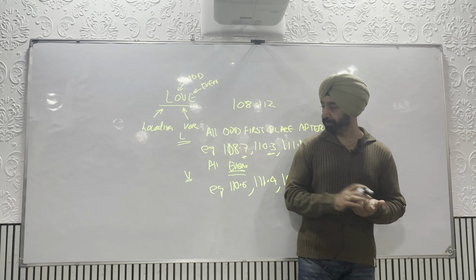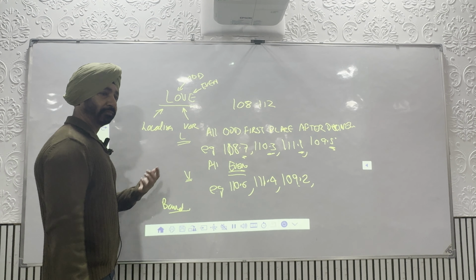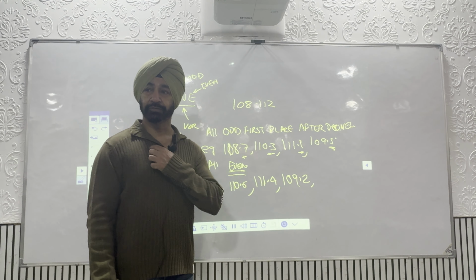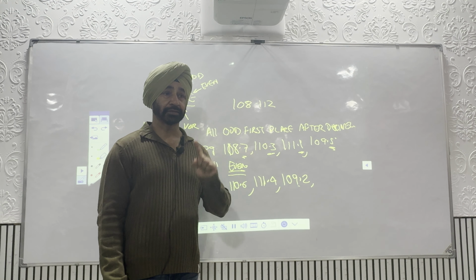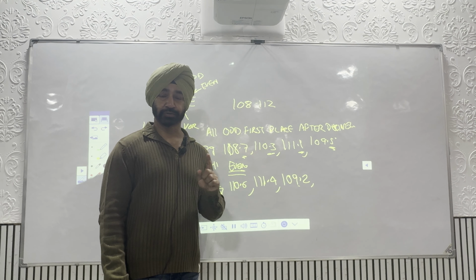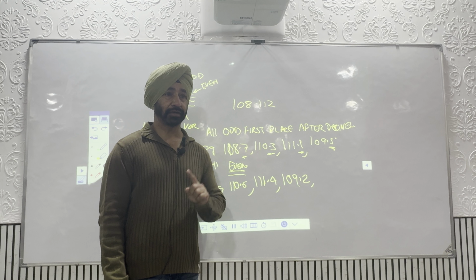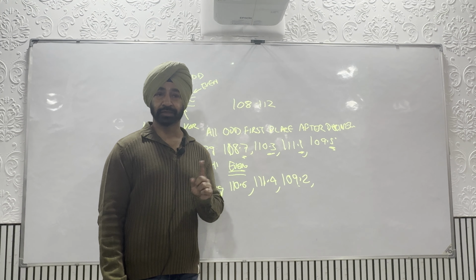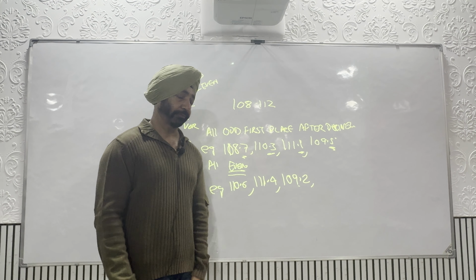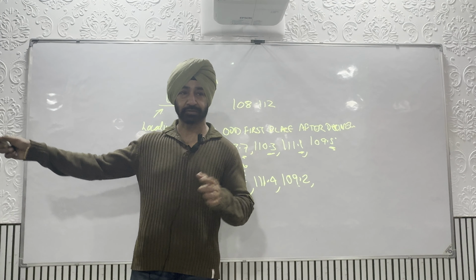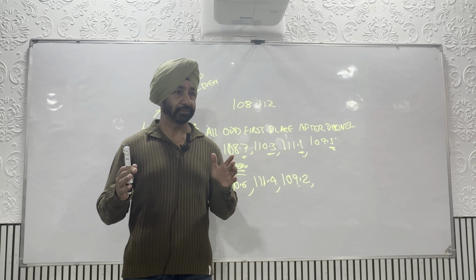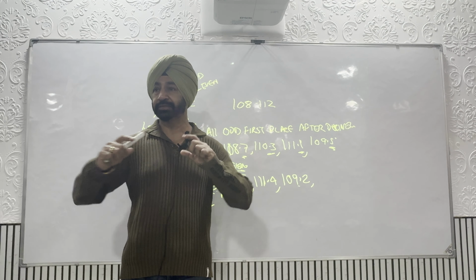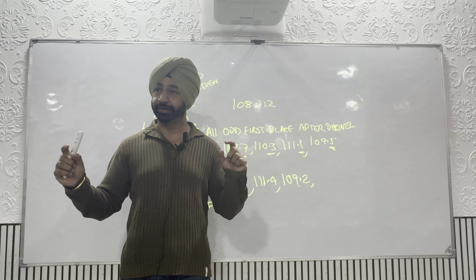Clear on this? Which band does it work in? It is from 108 to 112, we saw, and it is megahertz. It has to be in what? HF, VHF or UHF. Between 30 and 300, it is the VHF band. We have seen how this localizer antenna looks. It's an array. Array means something you put in sequence, that is called an array.